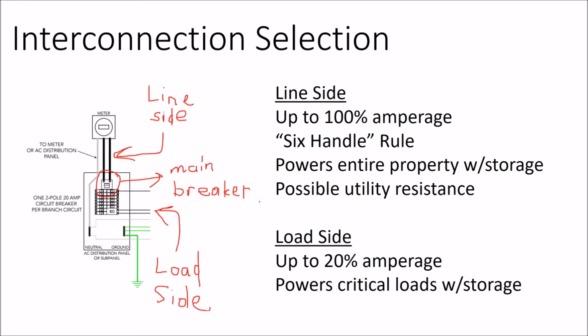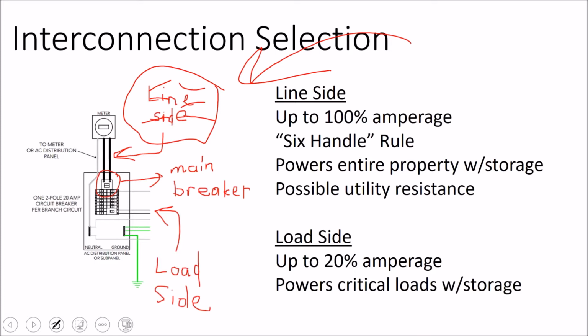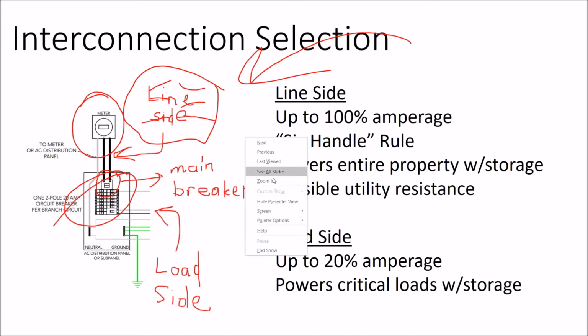on-site service panel, what manufacturers would call a power distribution panel or an energy distribution panel, that you put right here on your line side connection. This is not your main service panel. It is not considered the main panel, but it's between your meter and your main breaker. It's all on the customer side of the meter. So, from a dollars and cents perspective, whether you're doing a line side or a load side connection is all the same.